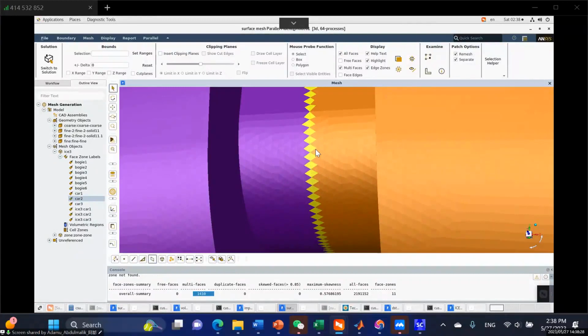It is a face that cannot be meshed, because we cannot find the aerodynamic forces on that face since it's already closed. What is the essence of that face? It's a redundant face, so the system is going to see it as a cause for error.